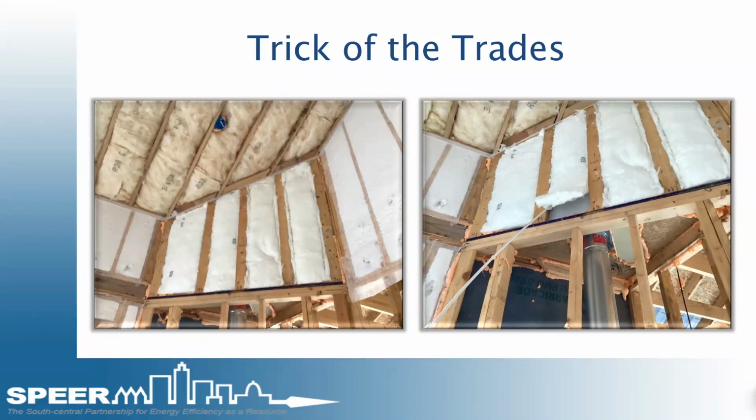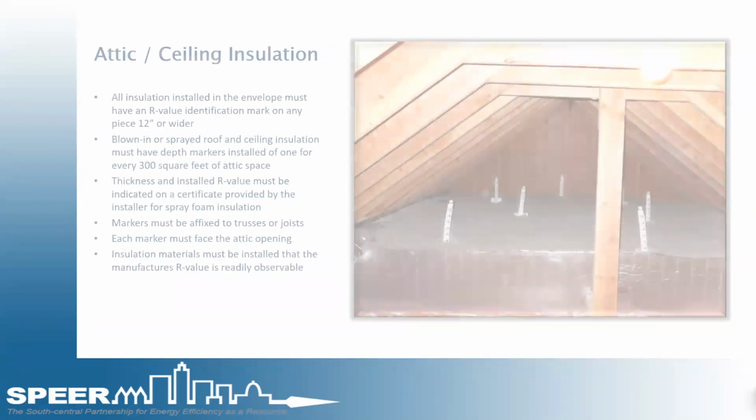But this is something that, from the surface on the left-hand side, if you were just doing an inspection and saw R15, looks like it's meeting the intent, meeting the requirement of code. Under further investigation, you pull that back with a little stick or anything you find there on the job site, and you can clearly see that it was split in half and not done accurately.